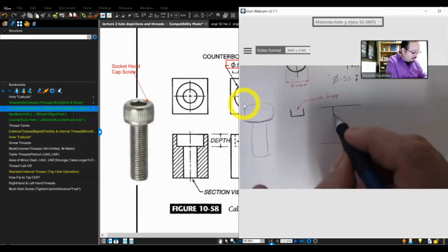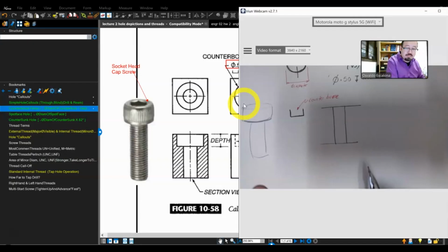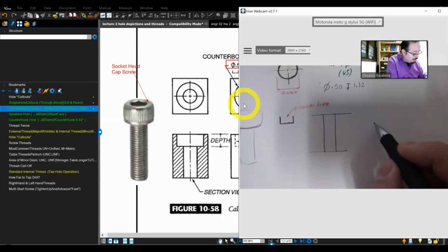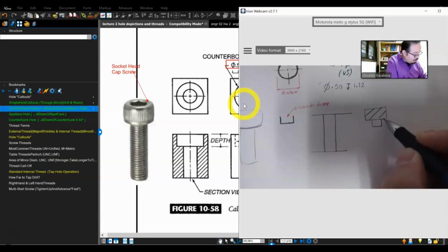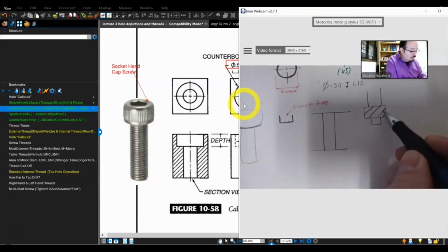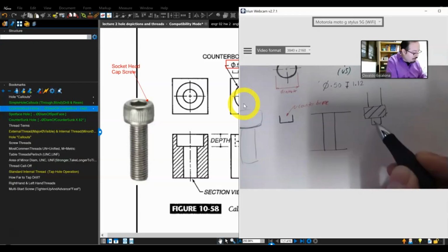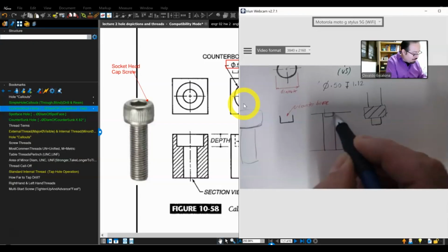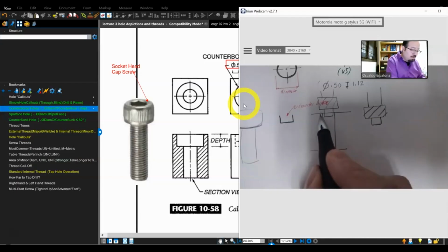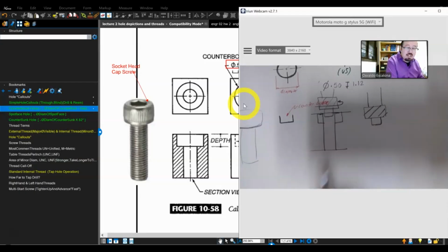I will go from the top and make a hole all the way through with my drill bit. And then I will get myself another bit, which is called a counterbore bit, and the counterbore bit looks like this. You will notice that it has these grooves to cut, not here, but here. You put it on top of the material and it starts moving around, and eventually starts cutting the material until it gets to the right depth.